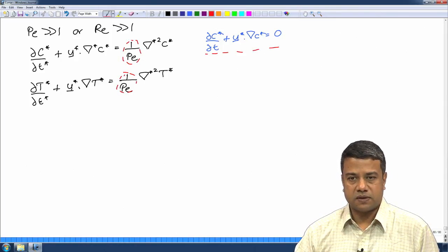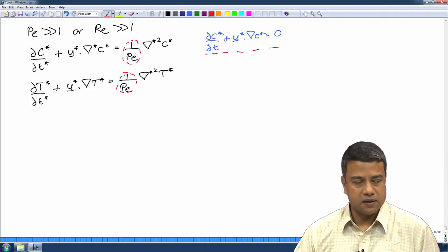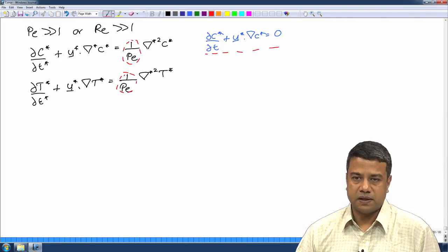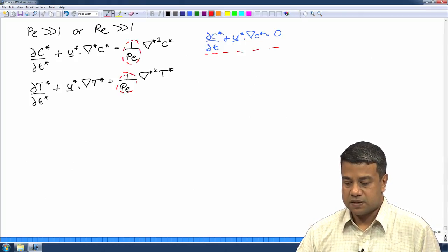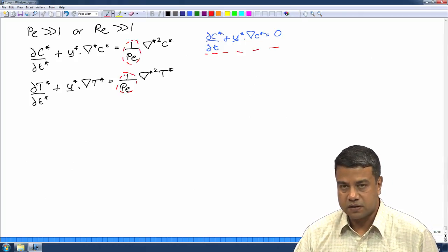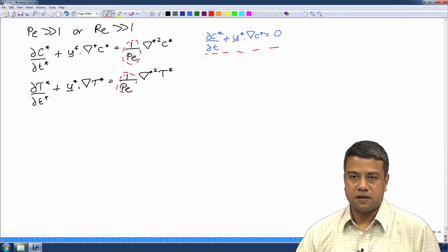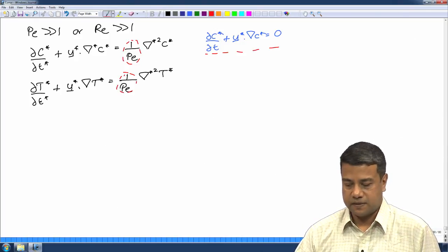We saw that when we were solving the oscillatory flow in a pipe. When you reduce the order of the equation, boundary conditions can no longer be completely specified. That is the mathematical reason why a solution of this kind is not correct.